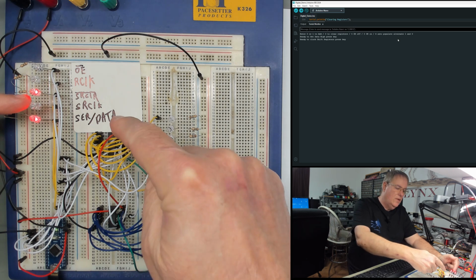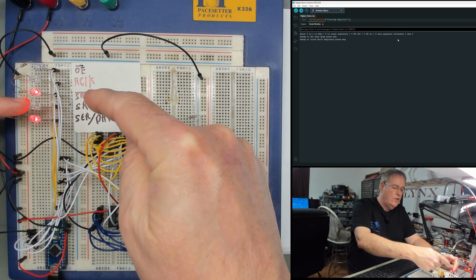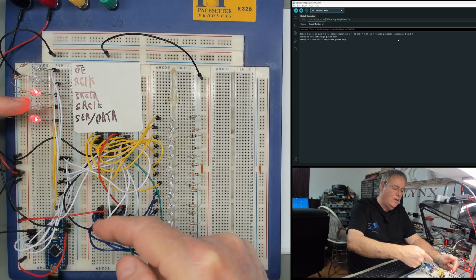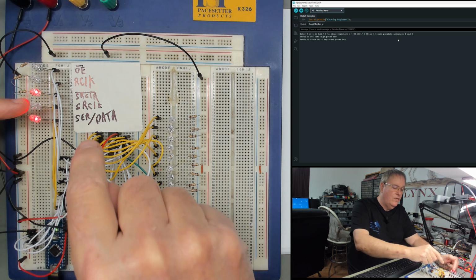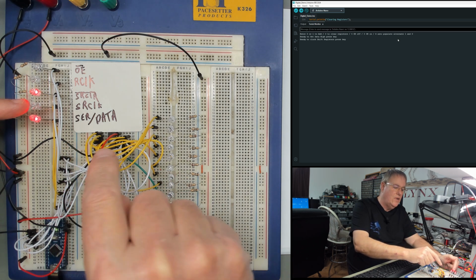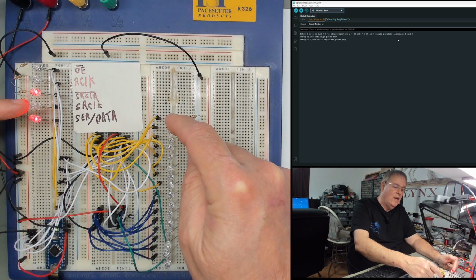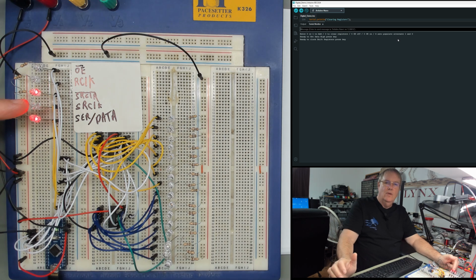And remember, the top chip, first register, second, third, fourth, right on down, and then it daisies over with one data line into the second chip and continues on. So we're going to be telling it to clock in that high into the first register on this chip, the top chip, which is the top LED here. Now, it's not going to light that LED. Remember, this is clocking it into the shift register.